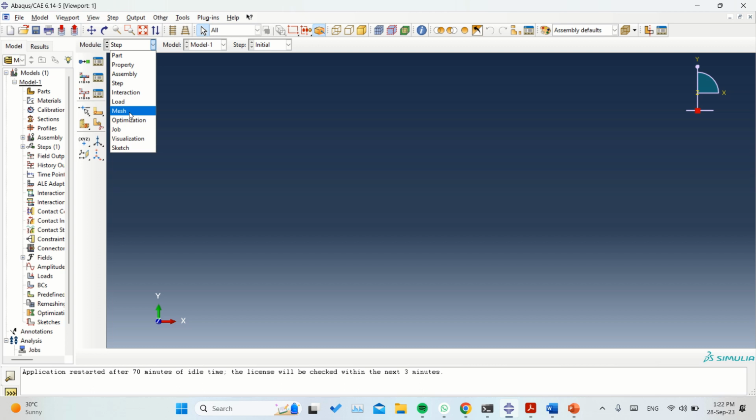Cut into pieces and work node to node, from one element to another. There are different types of loads and different types of elements. Detailed process. That is called meshing. Cut down your structure into smaller pieces, and then analyze them. That is called the stiffness method, and meshing is the process of cutting down pieces.